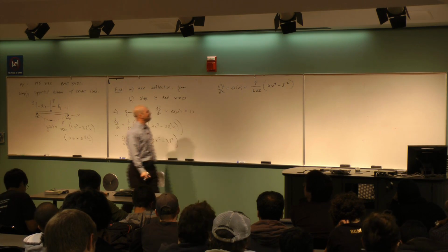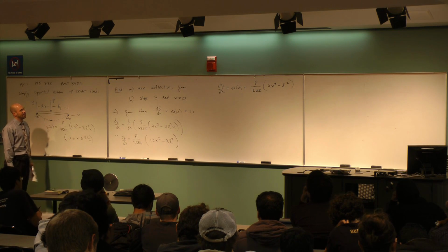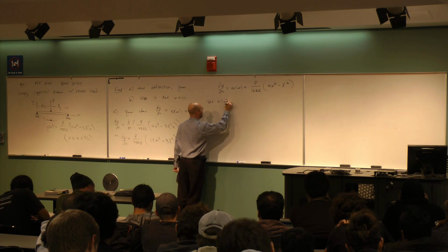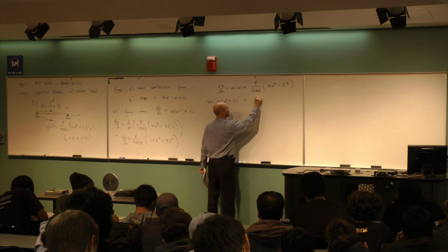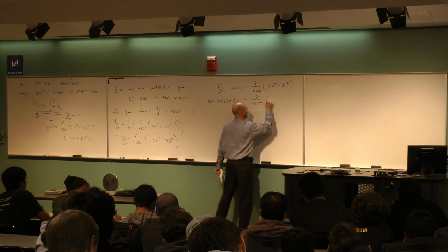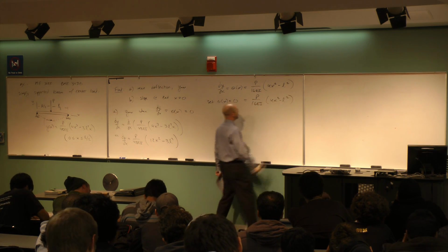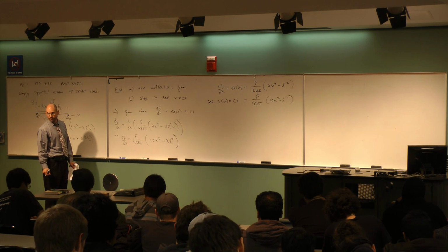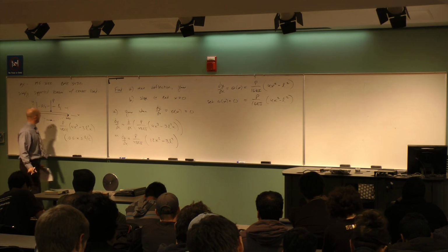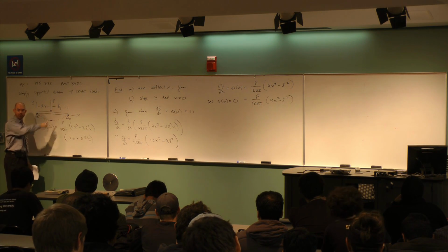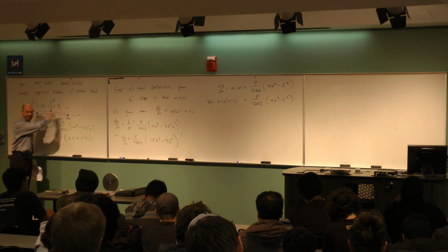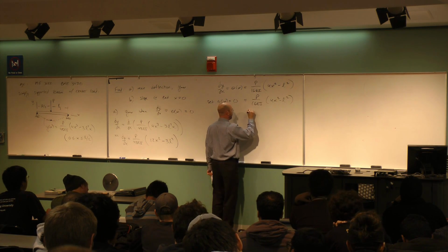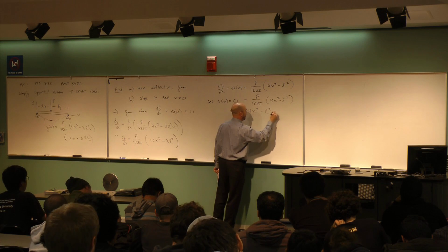So if I want to find the flat spot, I take that and I do what? If I set theta of x equal to 0, well, that's going to be P over 16EI times this guy, 4x squared minus L squared. Is P over 16EI equal to 0? Only if the load is 0, right? Incidentally, if the load is 0, what's the slope of this thing? 0, right? It's straight. Okay, so that's fine, but that's the trivial answer, so that doesn't matter. And so the possibility here is just this guy, 4x squared minus L squared equals 0.